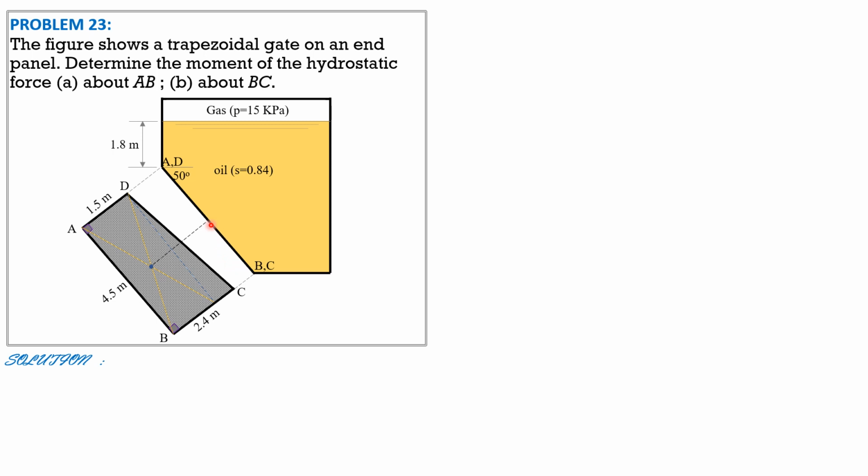Then this is the G of rectangle, G sub R. Then the location of the force is below, and that is CPR, center of pressure of rectangular area. It is where FR acts, and the distance between them along the plane of the gate is denoted by E sub R as shown.